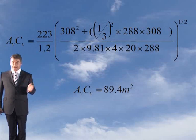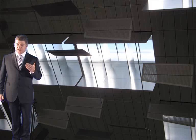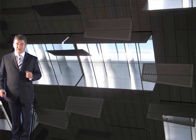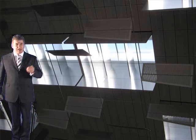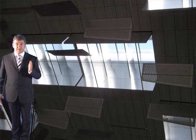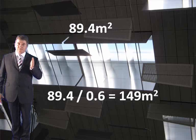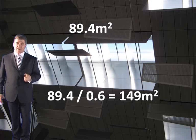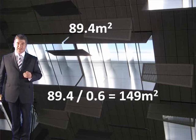That covers this step. Let's move on now to determine the number of ventilators we need to achieve that. So, we know what total area ventilation is required. Now, this is aerodynamic free area. In other words, you've got to take into account the coefficient of the ventilators, because ventilators are not totally efficient. So, what is the ratio of efficiency? Generally, the coefficient for efficiency is 0.6 for most ventilators. So, if we divide that by 0.6, we need 149 square metres of geometric area from the ventilators. Do you understand? That's what we actually need in geometric area, in physical area.